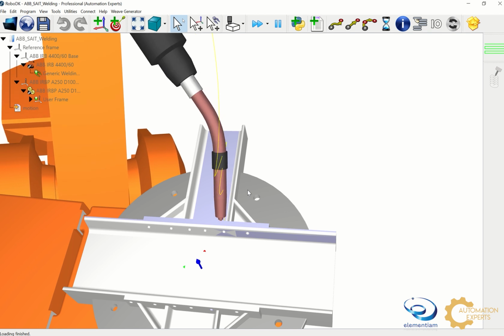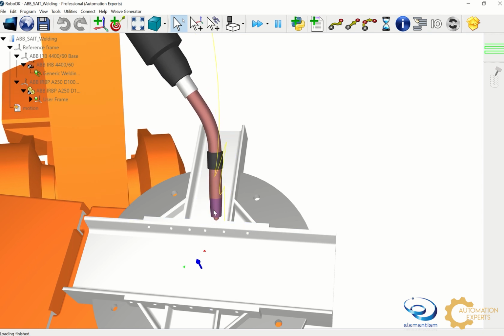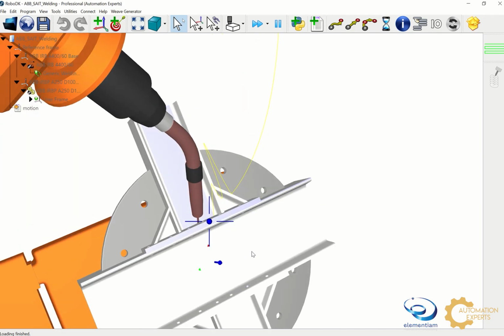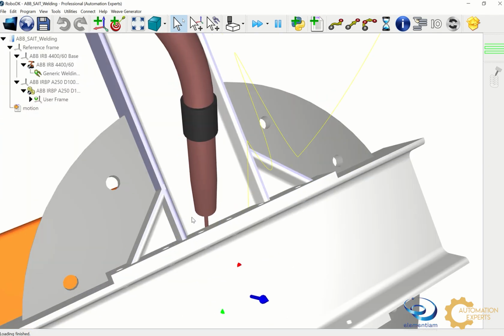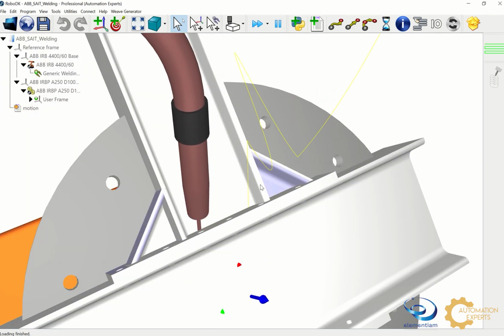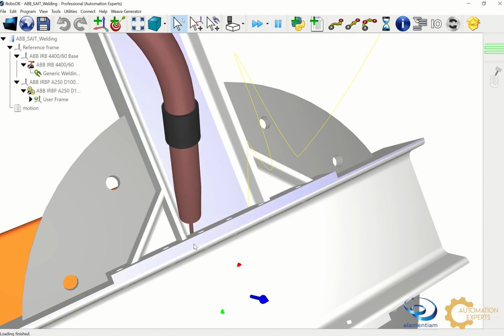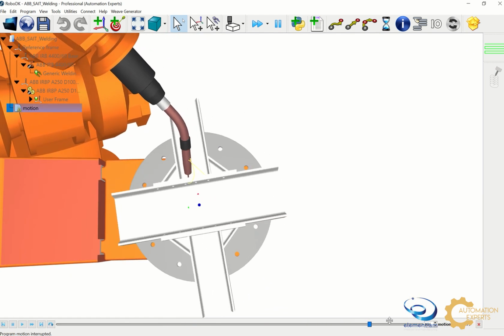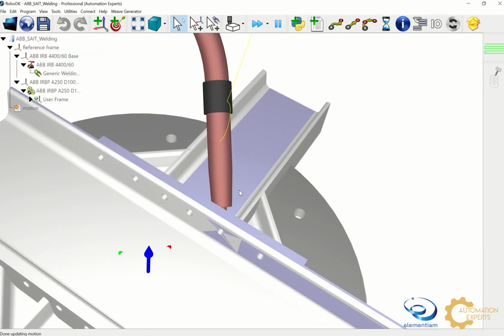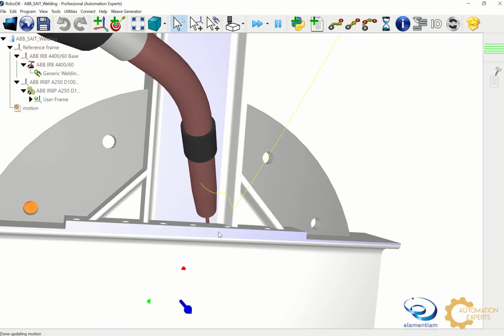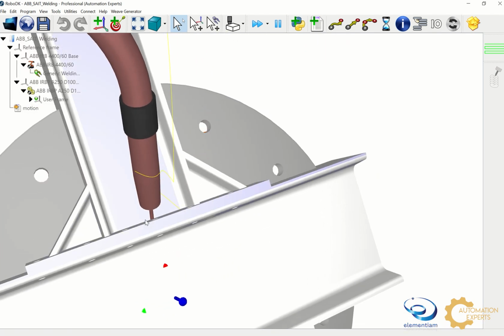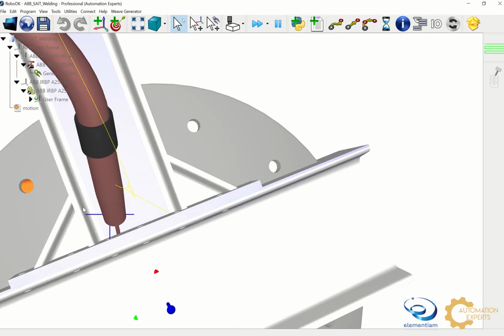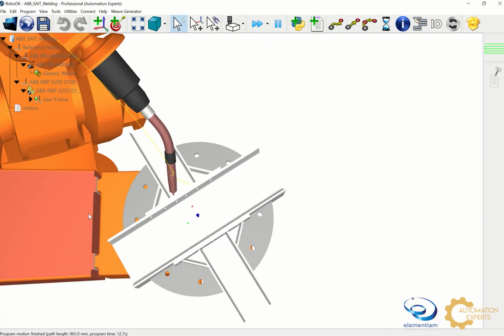What makes this technology invaluable to the structural welding industry is the ability to use 3D scanning on the robot to compensate for bad fit-up or parts that move. This adaptive automation allows us to further labor savings as fewer technical staff are required to operate robotic welding cells that have this technology. It also allows you to move from specialized fixturing to more generalized fixturing and potentially save on some of the storage space required to store all of those fixtures.